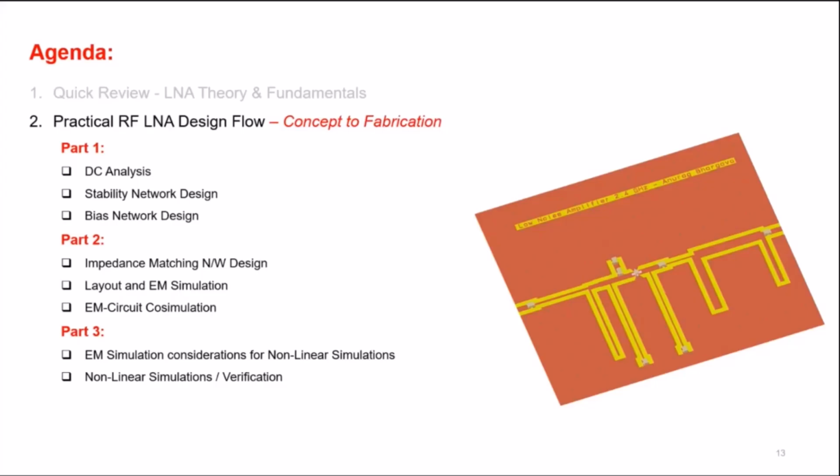Can you provide me a document on DC analysis, SI/PI, and thermal? Yeah, the local India team should take that action item. They can give you tons of documents. Then, how do we get the input impedance and capacitance from the GPDK? Of course, you can do simulations, S parameter simulation will give you everything which you need, and that's what you are going to see in the demo section.